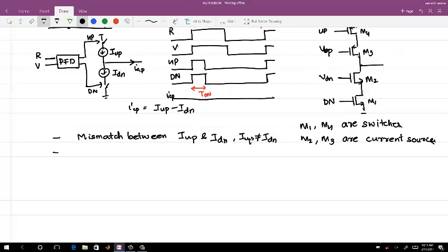Timing errors, how? Or dynamic errors. So you are a step ahead of this. What you say, dynamic errors arise because of what? Maybe a parasitic capacitance at all the nodes. What these voltages settle to initially and what these voltages have to be in a settled state. Right. So this is a system which has to be reset every reference edge, so the potentials will vary. That will be dynamic errors.